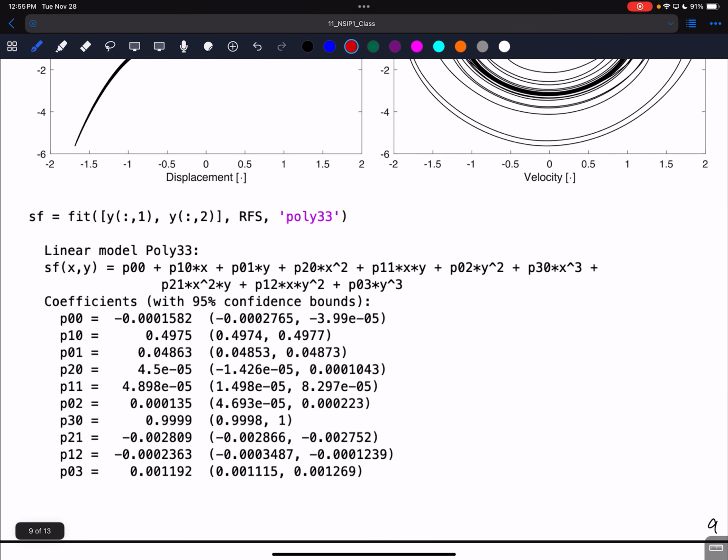So here we're just going to, again, fit a polynomial model to this. We'd probably neglect this. Here's our linear stiffness. Here's our linear damping. Neglect, neglect, neglect. Here is our alpha, and then we'll just probably neglect the rest of those if you had to decide.